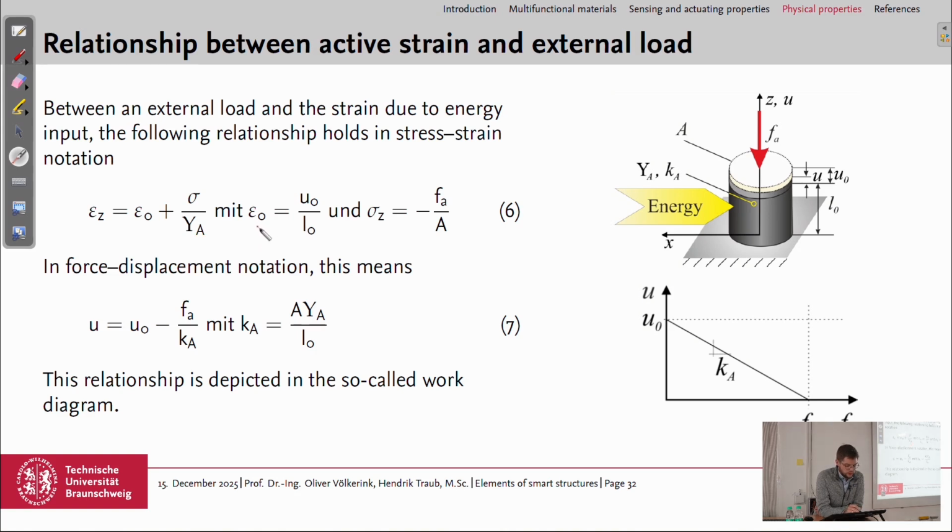And we can also put in that our free strain is the free displacement divided by the initial length. And we could also define that the overall stress in the material is the force Fa, so not the blocking force. This is Fb, but this is Fa, just an external force acting on the transducer, divided by the cross-section A.